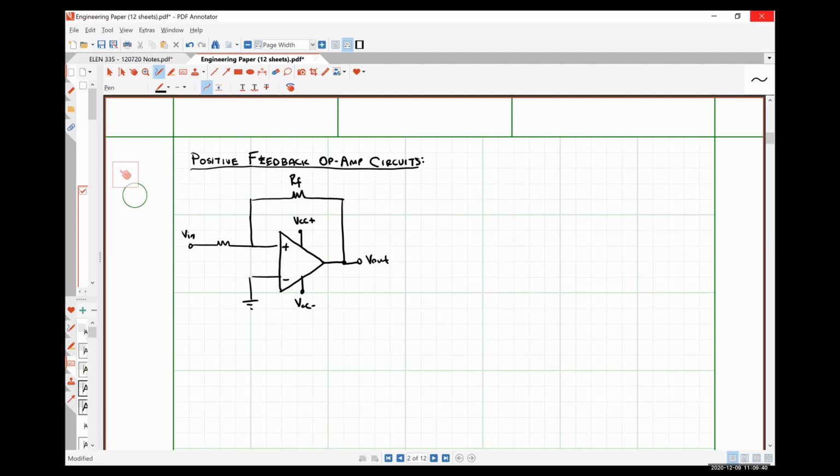That pressure wave gets converted into an electrical signal by a microphone. That then goes through an amplifier system and outputs an amplified version of your voice through the speakers. The speakers work by vibrating, creating another pressure wave. If the pressure wave created by the speakers gets picked up by the microphone as well, it cascades over and over again until all you're left with is that high-pitched squealing noise. That is a positive feedback scenario.